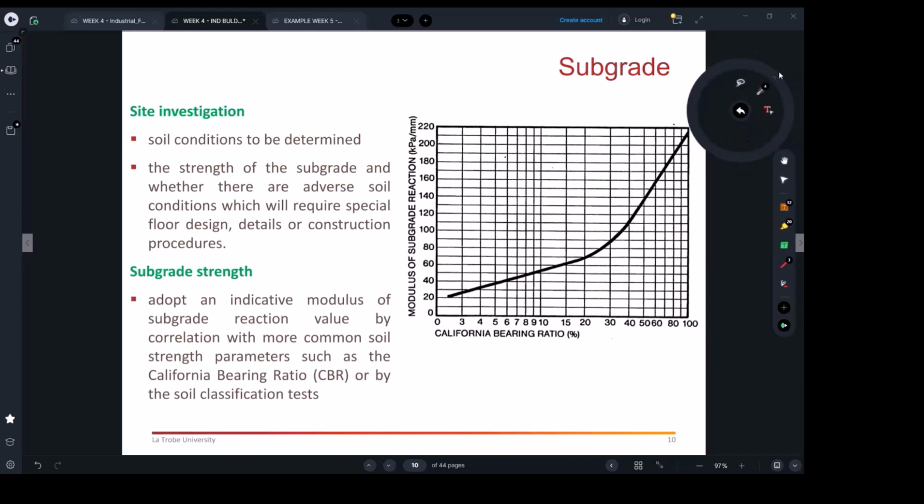The load is going to go from the object or whatever equipment you are moving above it, and then goes through the slab. The slab's job here is just to take the load safely from the top surface to the bottom. That's all it does. But again, the big problem is how the ground is working. So that's why careful site investigation needs to be looked at.